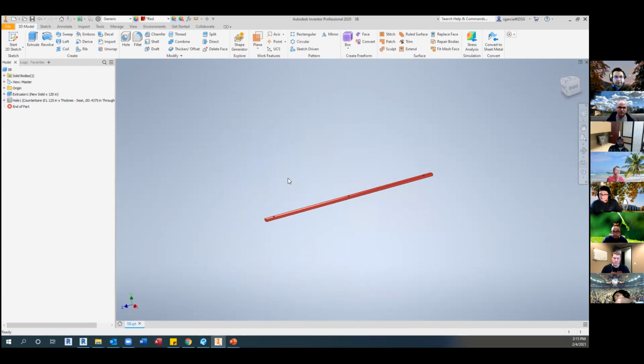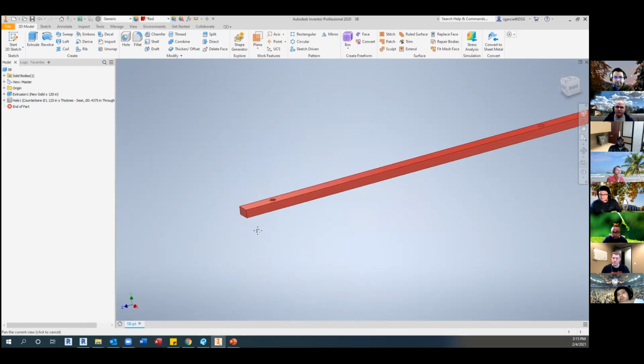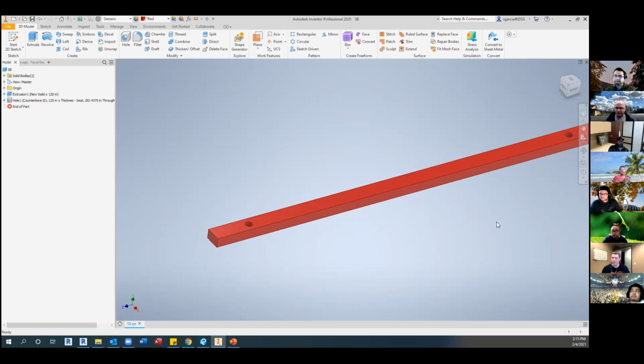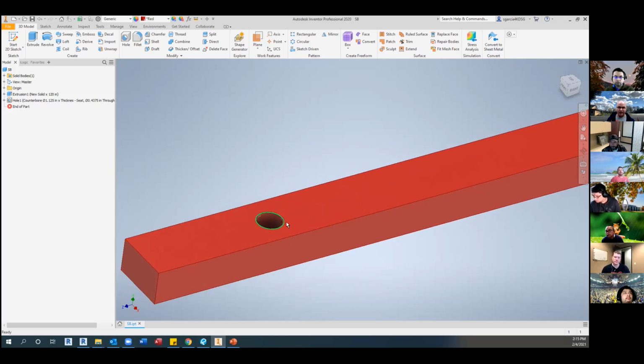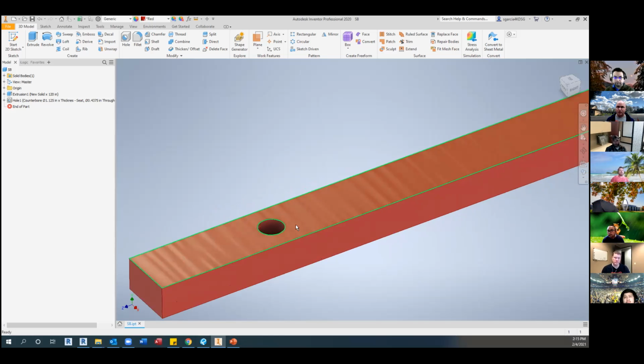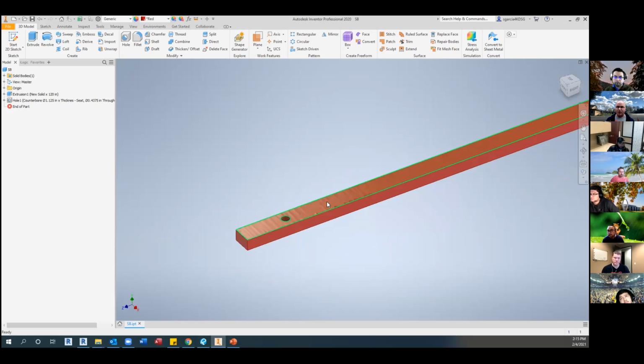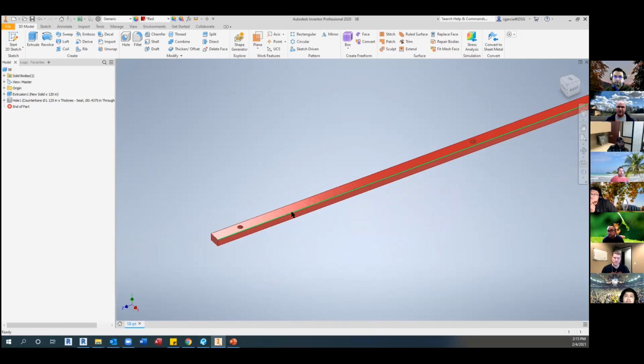Okay, so I don't know if you have any question, guys, before I move to the next stage. I do have a question, Saul. Yes. Let's say you've got the bar, and the way that you set it up is the width divided by 2 in order to get the center of that hole. But imagine now that your bar is getting wider because the mullion's getting deeper, but the relationship of the hole is not centered because it's got some weird offset on the system now. Would you have to change that parameter to be a specific dimension rather than letting it go to the center line? Yes, definitely. Yes, I can.